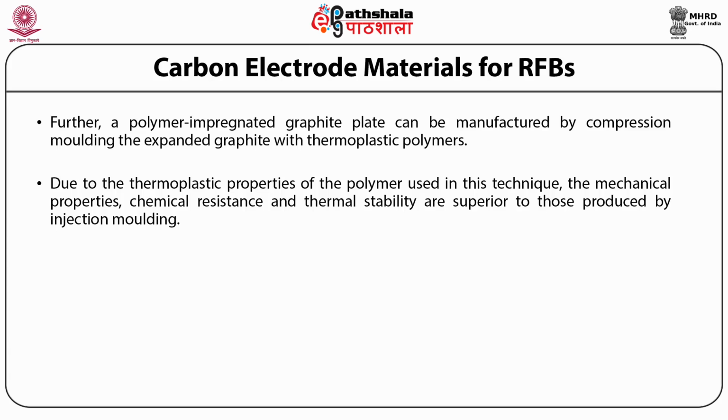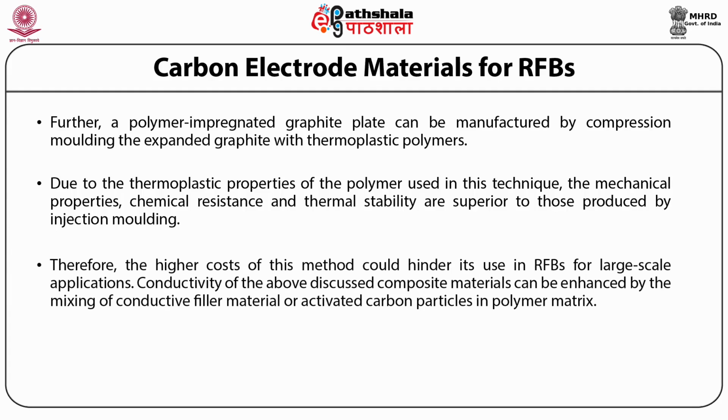Since longer time is required to cool down the mold before each half plate can be removed, the production cycle requires longer times. Therefore, the higher costs of this method could hinder its use in RFBs for large-scale applications.